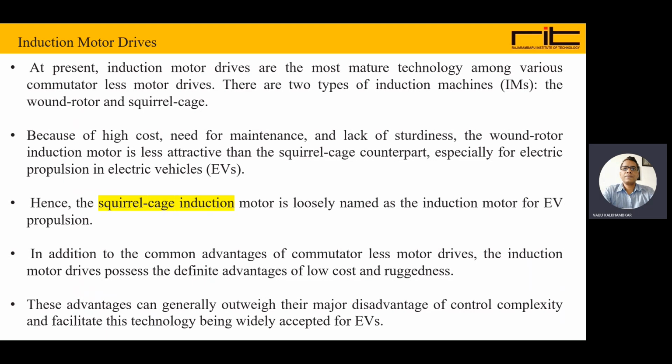In addition to the common advantage of commutator-less motor drives, the induction motor drives possess the definite advantage of low cost and sturdiness. These advantages generally outweigh their disadvantage of control complexity and facilitate this technology being widely adopted for electric vehicles.